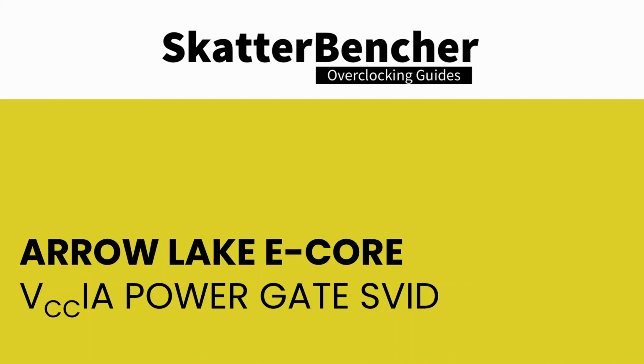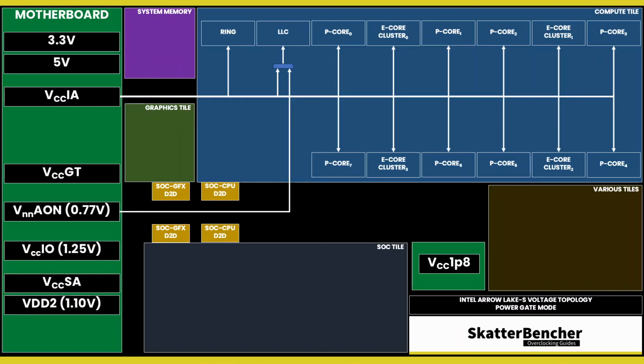In power gate mode, all the DLVRs tied to the VCC-IA voltage rail are bypassed, and the connected IP blocks are powered directly by the VCC-IA voltage rail. Power gate mode is basically how the VCC-IA voltage rail worked on the previous generation, Raptor Lake. For Arrow Lake, it also works, but it's a little bit complicated.